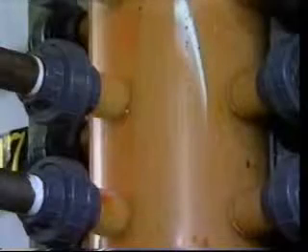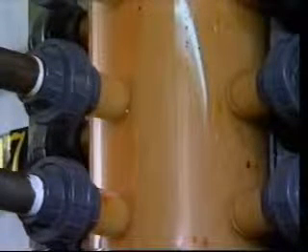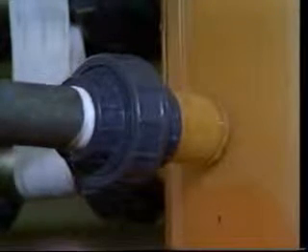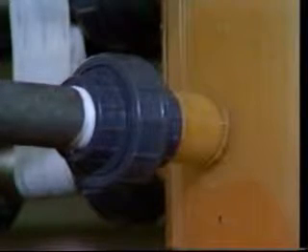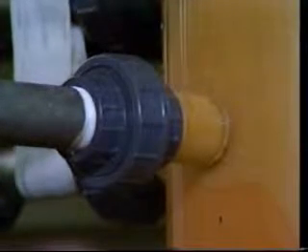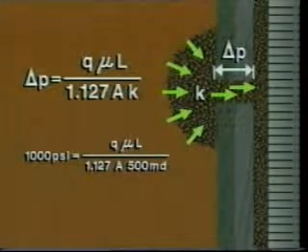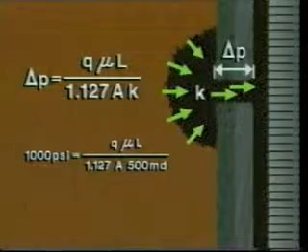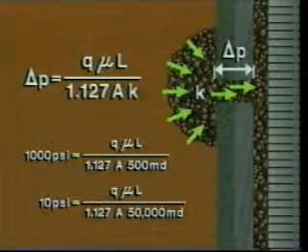Now that we have discussed some of the concerns regarding gravel placement, let's consider the flow of reservoir fluids through the packed area and into the wellbore. The greatest pressure drop generally occurs where the produced fluids flow through the perforations. This pressure loss in the perforation channel is due to the convergence of the produced fluids from radial flow into a linear flow pattern. Darcy's linear flow equation demonstrates the importance of placing a highly permeable gravel pack in the perforation tunnel.